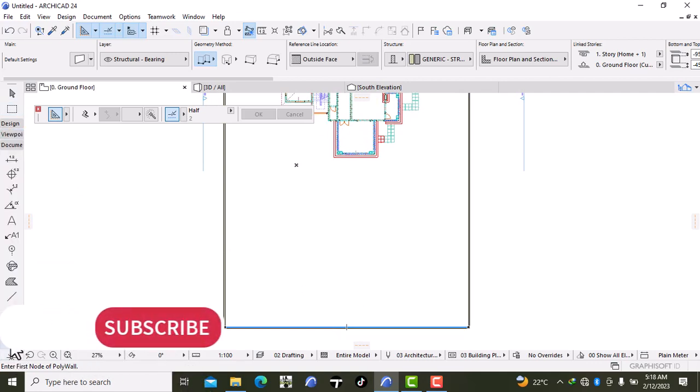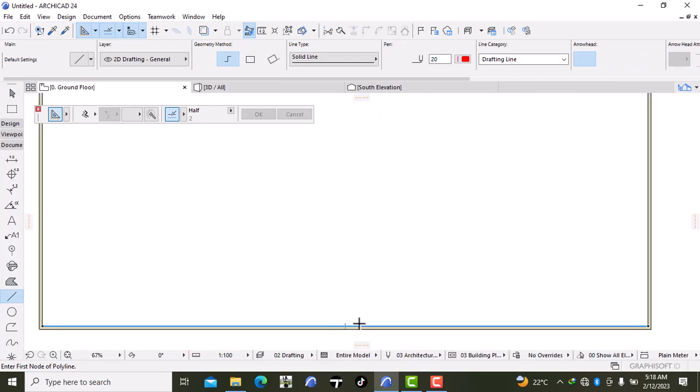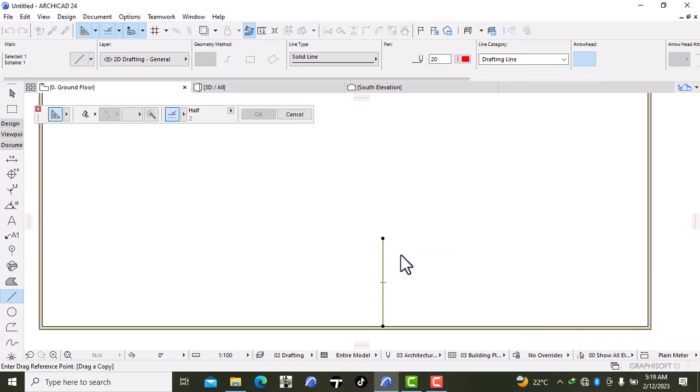So I can just go back with this document tool, and from this center over here, from this point I can drag a wall, maybe 2500 on this side, and that line tool right over there. And shift Control D, Control D, okay, and the shift, escape, just hold on to the shift button, then Control D plus, and just drag this at a distance of 5000.